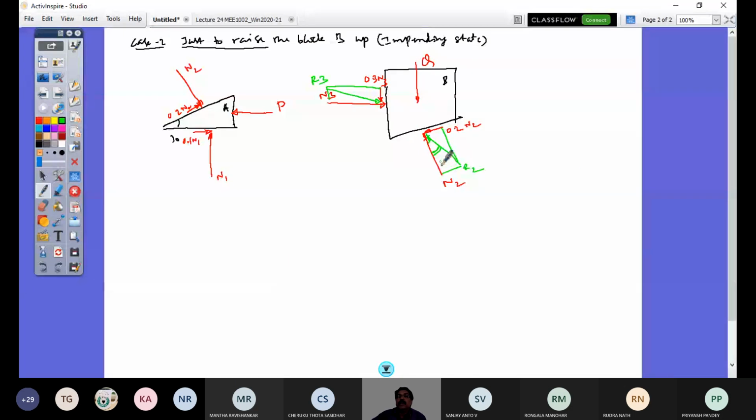So this angle is 11.31 degrees. And you see here, interestingly, this normal to the vertical would be 30 degrees. So the direction of R2 is now 30 plus 11.31, so it's 41.31 degrees to the vertical. Whereas in the previous case, it was the difference, right? And here, what would be this angle? This angle is 16.7 degrees. But the direction now is down.